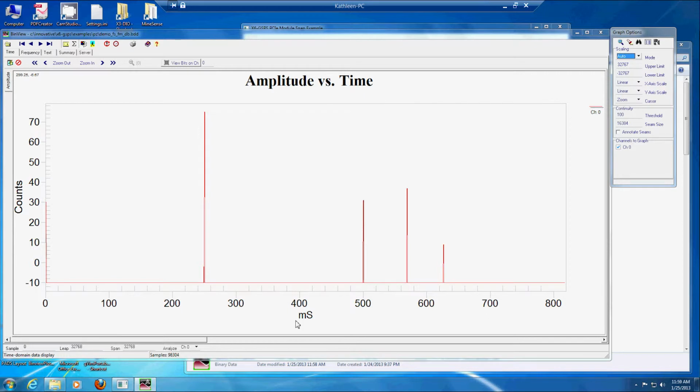So in this first frame, the carrier is shown at 250 megahertz. You also see the second harmonic, which is output from the signal generator at 500 megahertz. The image frequency of the carrier is shown here, and because it's outside the band of interest, it only has about 45 dB of attenuation.